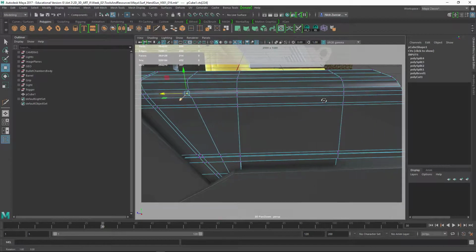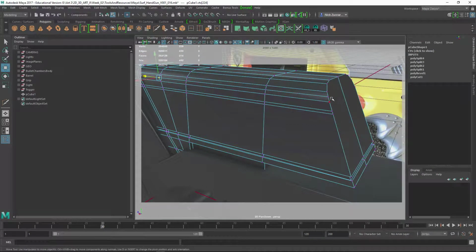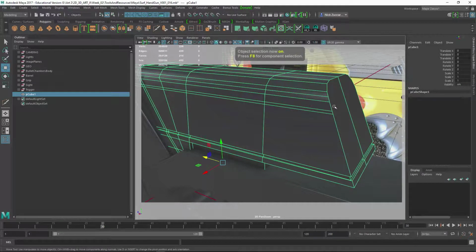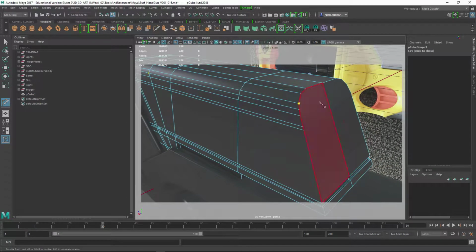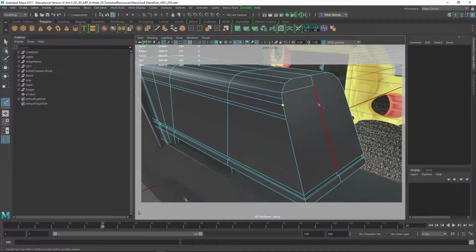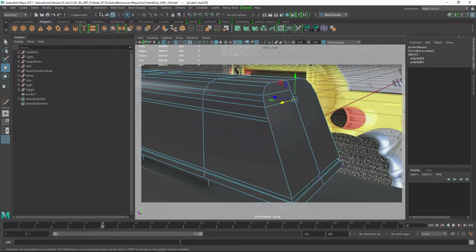So what I'm going to do is something similar to what we did before. Try to do an extrusion going all the way through the thing. If I do that, I'm going to use the multi-cut tool and take these lines and continue them straight across like this. Oops, let's undo that. Just going to run this and hit enter. All I got to do is take that vert and snap it here and then snap it right down in the center, and we know we're running straight across that thing. I'll do the same thing for this and that right there, like that.